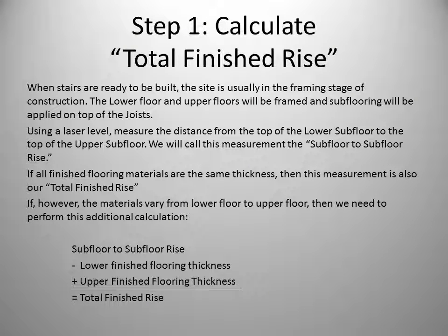The first step is to calculate the total finished rise. When stairs are ready to be built, the site is usually in the framing stage of construction. The lower floor and upper floors will be framed and subflooring will be applied on top of the joists. Using your laser level, measure the distance from the top of the lower subfloor to the top of the upper subfloor. We will call this measurement the subfloor to subfloor rise.